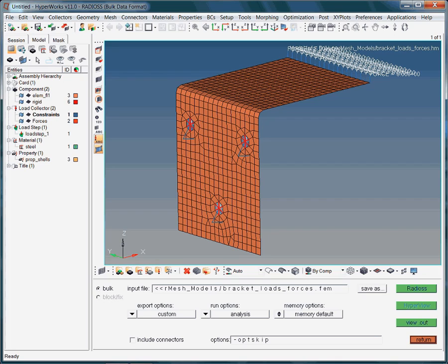Second, pursue a visual check of the model by employing the model browser. Just compare the color of the force and constraint symbols. Also disable and enable constraints and forces from the display. Well, to shorten the debugging steps, I want to draw your attention to the color of the force and constraint symbols. Do you see the problem? The answer to the problem is that, by accident, the forces are stored in the constraints collector. However, I guess by now you know how to solve this issue.